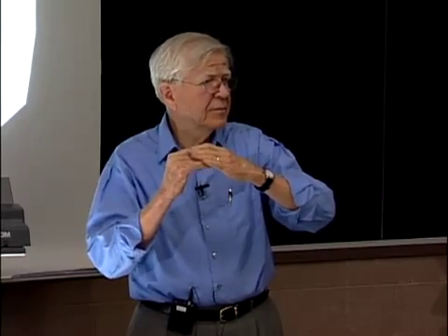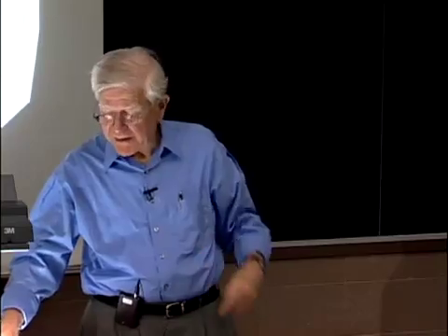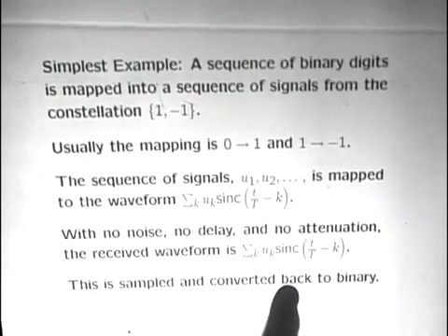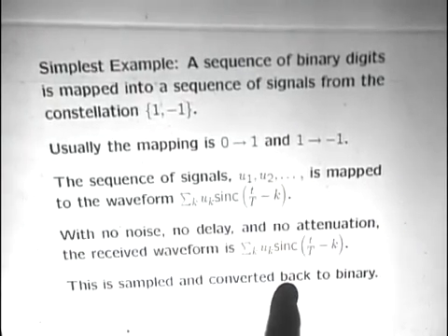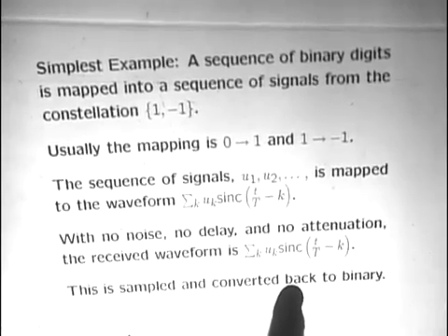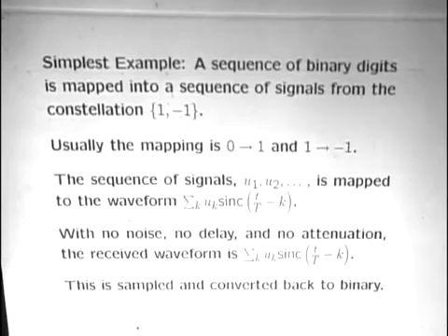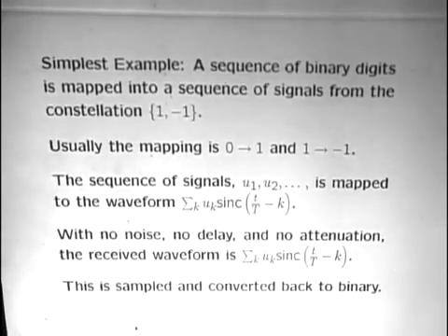signal. An easy way to deal with that is to assume that there isn't any attenuation in what you're calling the signal, because you're going to amplify that to a reasonable value to operate on it anyway. So in fact, you're amplifying the noise. So the only thing you're interested in is what's the ratio between the signal power and the noise power.